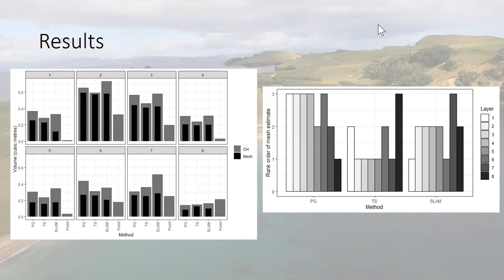So if you have something like a drain feature, where it dips down at the bottom of a trench, you're going to get a nice smooth bathtub across the whole bottom of your trench. It's not really going to account for where the surface of a trench goes back in a concavity. So you're going to get an overrepresentation of the volume.